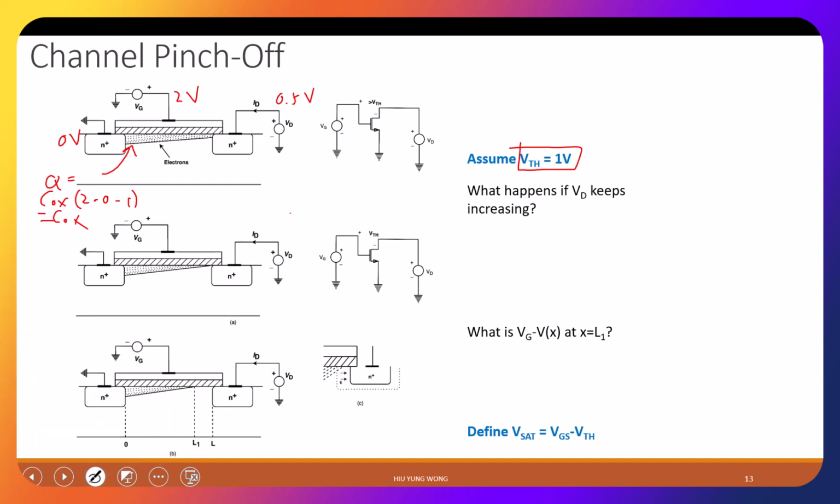Now I try to look at the charge here. What do I get? Cox times Vg is 2, but now it is 0.5 at the channel, and this is 1, so I only get 0.5 Cox. Make sense? The main point is because my channel potential keeps increasing from left to right, and as a result, the charge I can induce is less.